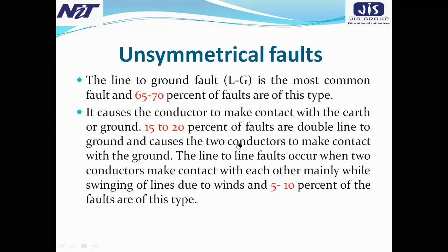Then what happens? The sagging will come, the line distance will increase. If a river is beside that area, huge airflow will be there. So there is a chance for swinging of line due to this wind. For that reason, you have to face the problem and apply your general knowledge and take some decision to avoid that type of fault. If you want, you obviously can do that.